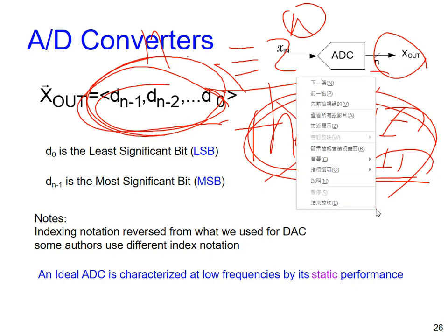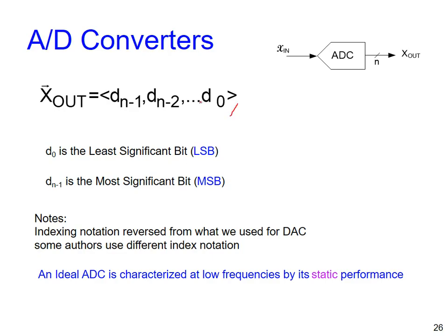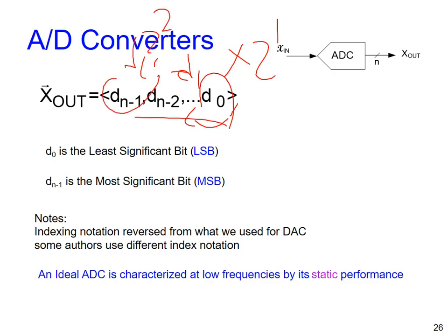Okay, so for binary weighted, 2进位权重式, it means from each bit to the next, the weight will be doubled. And from D1 to D2 also doubled, right, all the way. That's it. So the last one carries the most weight, right? So we call it the most significant bit.